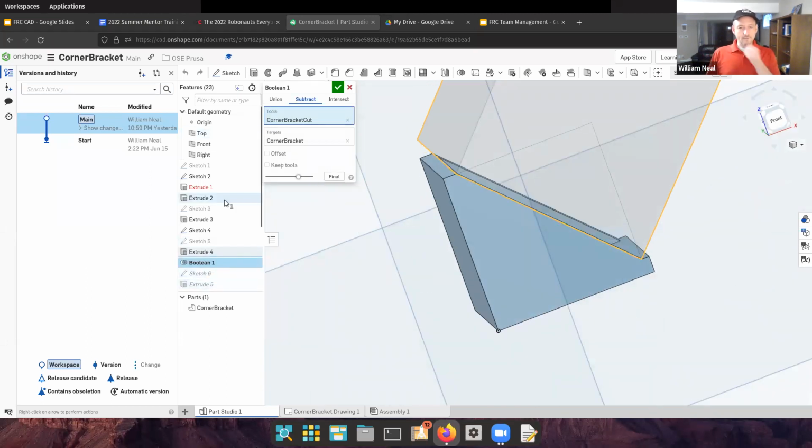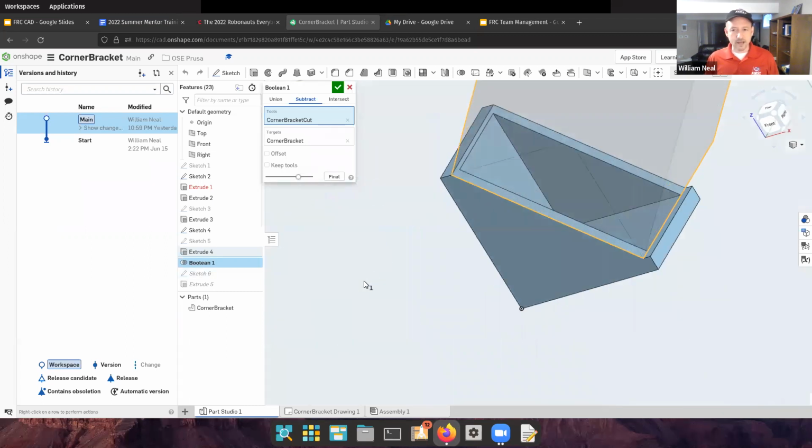And so what I'm getting at here, you make a sketch in 2D, you extrude it. Then you may make another sketch on that item or separately, and then you may extrude that. And then at a certain point, several of your objects may intersect using Boolean operations, and the intersection may be kept or cast away depending on what you want. And through this repetitive process, you gradually build up parts.